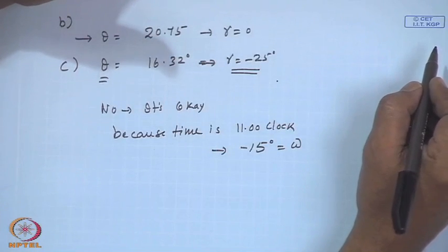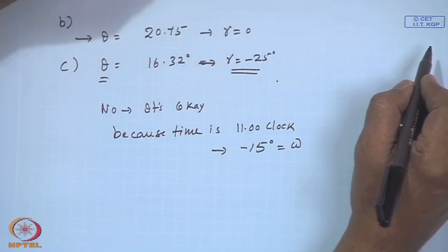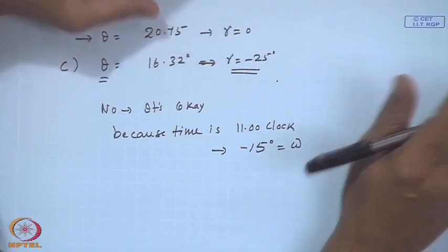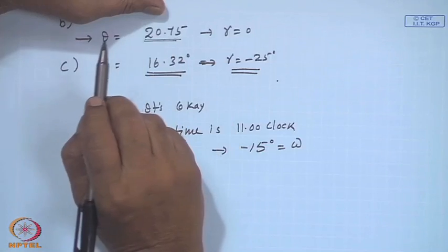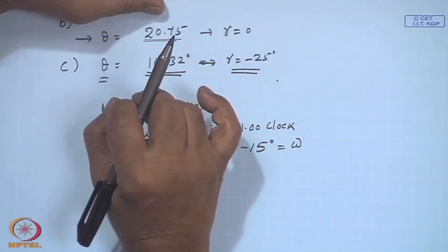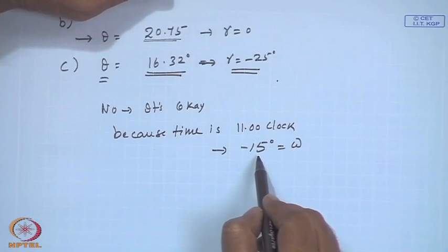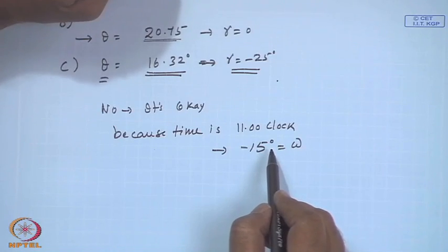So, you are towards east and you have oriented beta fairly well. Consequently, you have a better angle of incidence compared to even the south facing surface. If you do the same calculation at omega equal to 0, the south facing surface will have a better angle of incidence than the one with gamma equal to minus 25, right. Better angle means theta is lower.